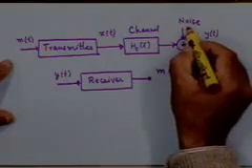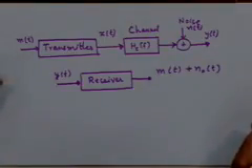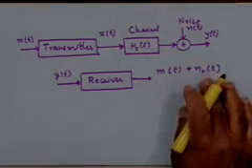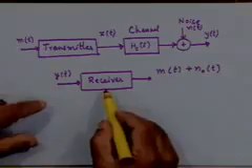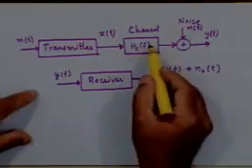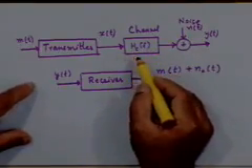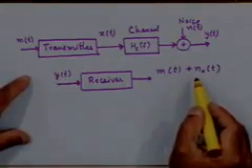So there is an input noise n of t, and the receiver will try to eliminate as much of this noise as possible, but there may be some residual noise still left which we denote by n sub o of t. The receiver has to process the incoming waveform y of t so as to remove the distortion that might have been introduced by the channel, and also to eliminate as much noise as possible, right? That is the main job of the receiver. Okay, so this is the model, this is the framework in which we'll carry out the discussion for most of today's class.